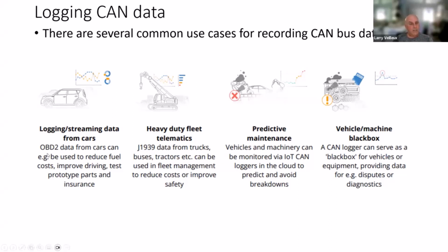And there's a specific port in your car. A lot of cars will have it on the left side of the dash, where you open the door and pop off a cover and see a connector inside. That is an OBD2 connector. And that function with the OBD2 connector could be like a built-in logger. Maybe it's not logging all the CAN messages specifically, but it's logging all the error codes and different codes. Then you can plug into it, download that and analyze it.